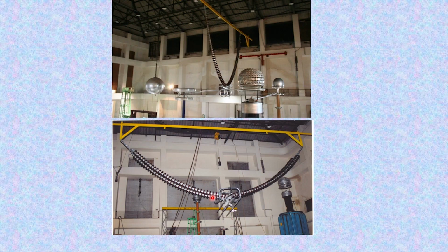Practically, making the entire string uniform is highly difficult, because it depends on the stray capacitances from the ground to the insulator string, from the tower to the insulators, and also the coupling between each of the insulators, where you have a capacitance. So, ideally making it equal is very difficult, almost impossible. So, proper grading is done with the help of corona control rings and arcing horns near the ground end. This will help to reduce the stress on the insulators, particularly those connected to the high voltage or near the high voltage end.